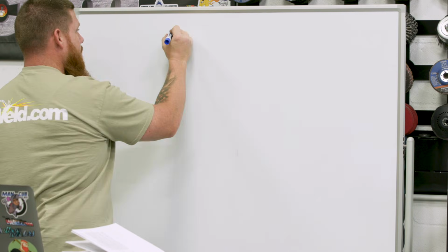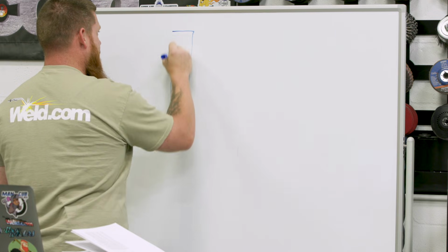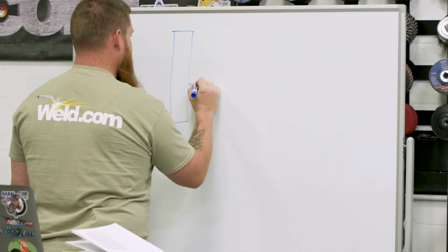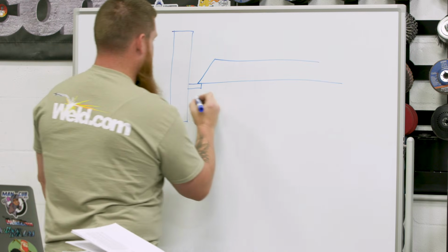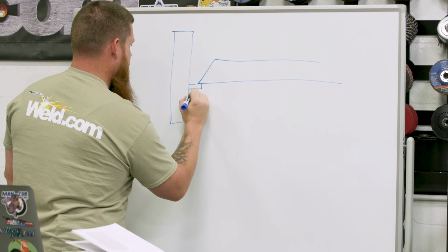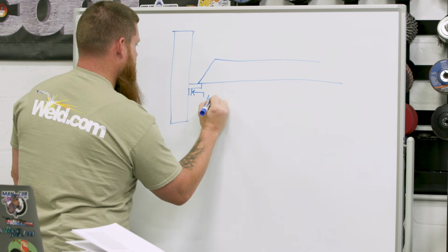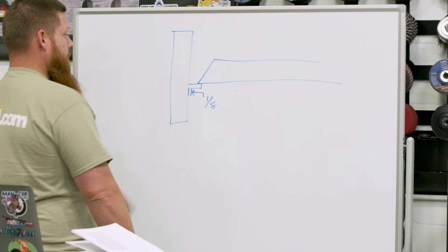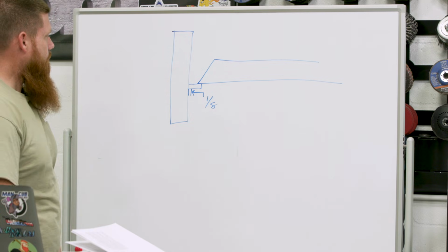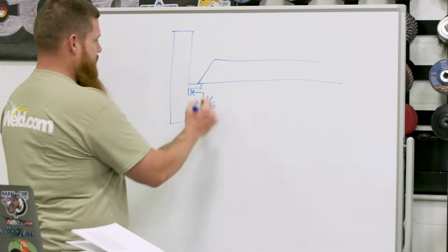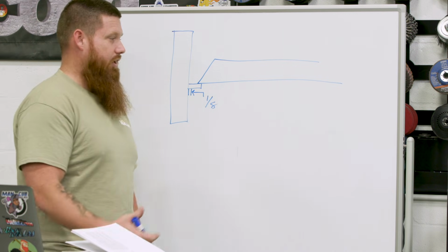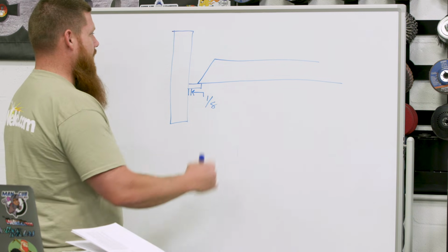Okay, let's say I'm out on a job site, and a lot of you welders probably ran into this. Your fitter is having a bad day, right? And you're supposed to join two pieces together, and you're supposed to have a 1/8 inch gap right here. I can't draw today. Couldn't draw yesterday, no excuse, right? So you're supposed to have a 1/8 of an inch gap here. And the CWI comes out and he measures it and he's like, nope, what you actually have there is 1/4 of an inch. So they can get a hold of the engineer, him and the engineer can talk it out and what they can do.